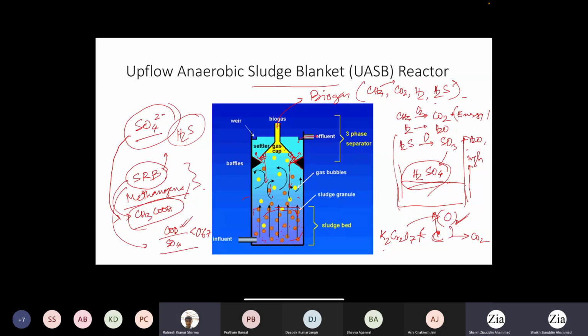Now, experimentally, COD value will always be greater than BOD? Yes, that's the case, but in some cases you can actually get equal values also. Suppose you have a glucose solution, and in the solution you don't have any other component. You know glucose is completely biodegradable, so whatever BOD value you get, you will get exactly the same value of COD also.